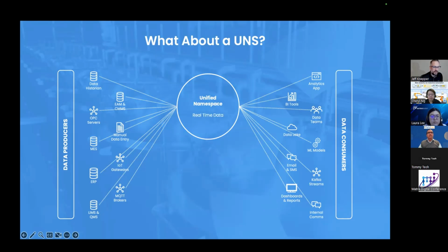The issue is that the unified namespace won't solve this problem because it's focusing on real-time data, not ingesting, connecting, cleansing, adding operational context, identifying events, aggregating KPIs, validating results, or distributing. The UNS is just a flow of real-time data out to the application, which means those steps still live out at the application in order to combine data from multiple sources, aggregate results, and identify value-added information.